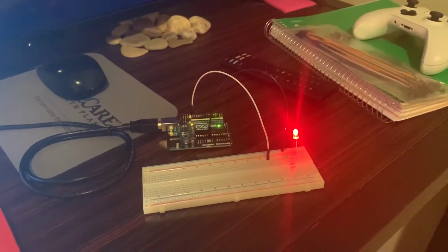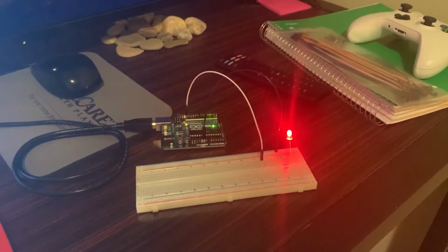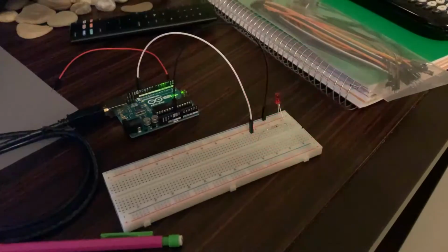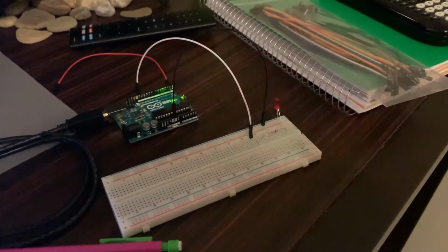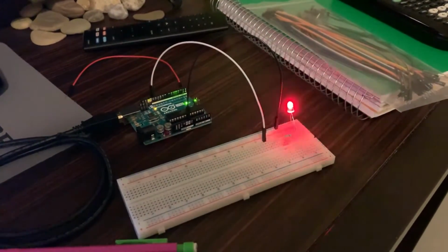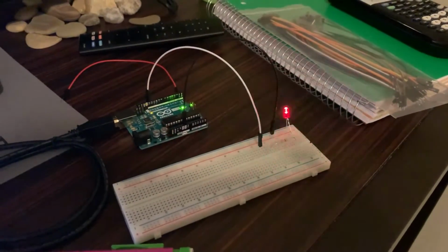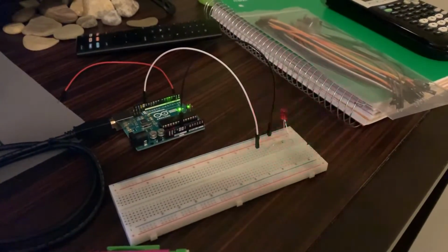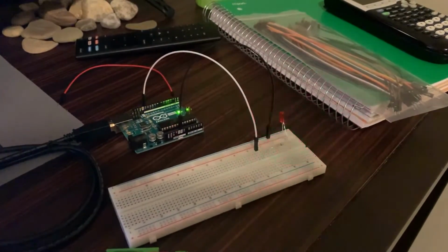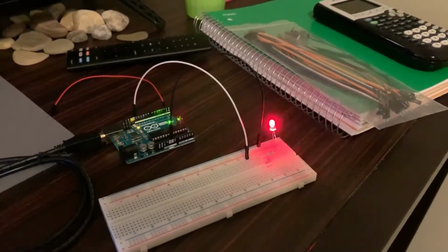Here's blink, where the LED will be set to high for 1 second and then set to low for another second, and repeat. Here we have an LED blinking at 40 milliseconds on, 40 milliseconds off. The fastest that I could see the LED blink at was at 13 milliseconds on, 13 milliseconds off, which falls at around 40 frames per second, which is in the range of 30 to 60 frames per second, which is considered the fastest an eye could see.